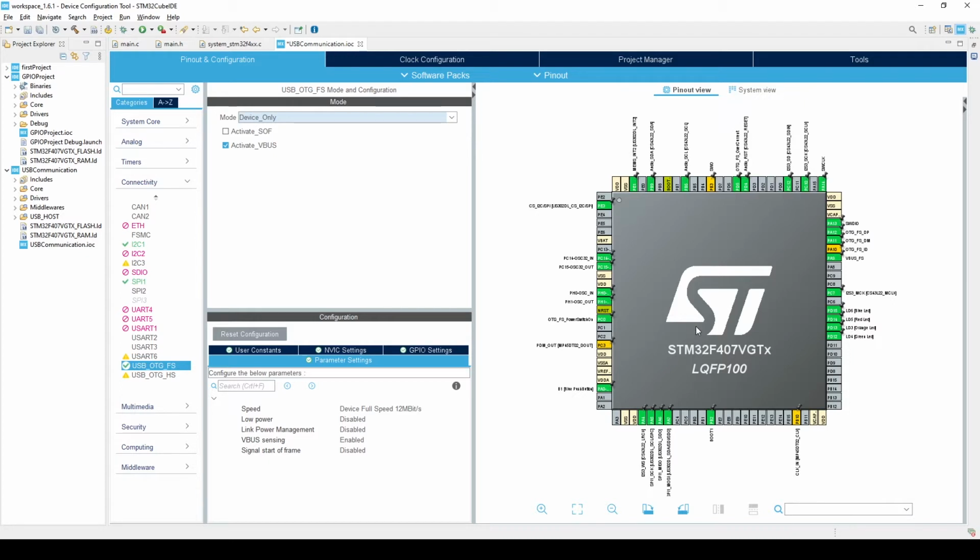So okay, we had this config, and let's talk about this USB communication controller that I told you. Inside your microcontroller, you have a section that is controlling the communication via these two pins here. So this is the D plus, this is the D minus, and these are connected to a USB controller. This USB controller uses these pins to communicate with the PC that you have, and this is basically the physical layer that is needed for communication.